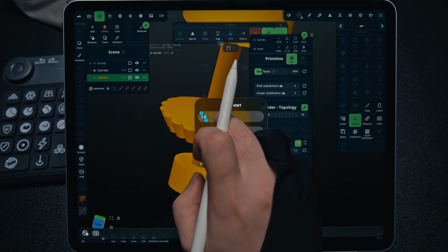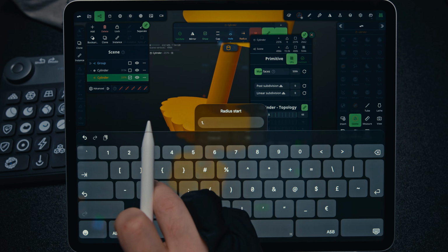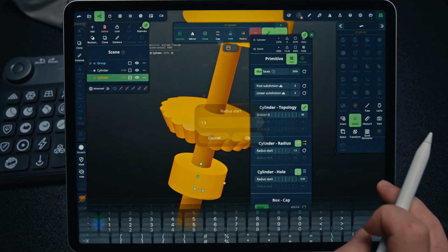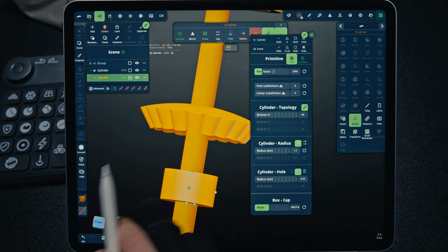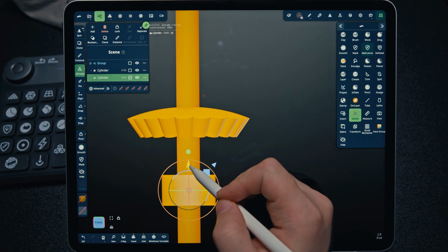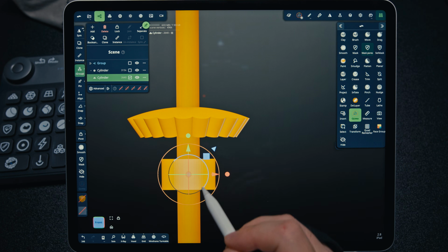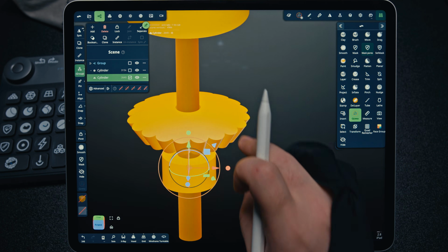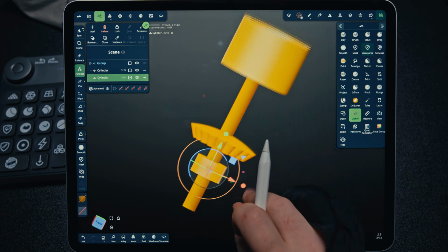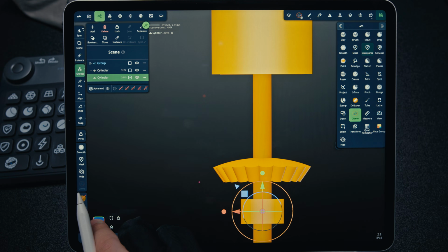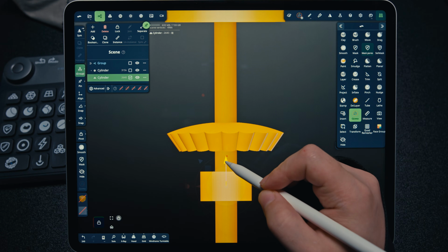I think a 3 mm diameter is also too much, so I'll reduce it to 2.6 mm. The wall calculation is (2.6 minus 0.9) divided by 2 equals 0.85 mm of metal thickness at the thinnest point. So, as you can see, everything relies on math and calculations.